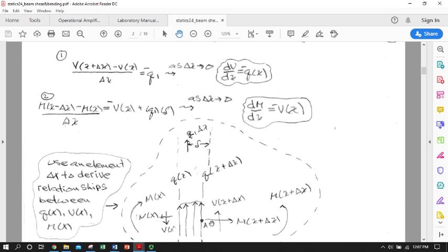If we're talking about weight or some kind of loading that you're supporting against gravity, the distributed load would be downward and then this negative sign would go away. This negative sign, however, is inherent to the definition given the assumptions for positive values on the right-hand and left-hand side. So never forget that. This one is going to be independent of your distributed load direction, especially because the distributed load went away. So these are your two workhorse go-to equations.